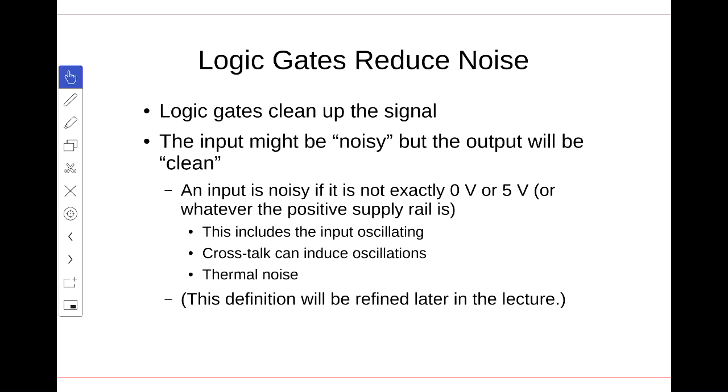Where does this noise come from? Well, it could come from previous gates not doing their job. Could come from crosstalk. Remember we mentioned that digital design, once you hit the PCB, becomes analog design. As soon as you run traces on your PCB, they are transferring information using electromagnetic waves. It's actually got very little to do with the electrons zooming along the copper traces.